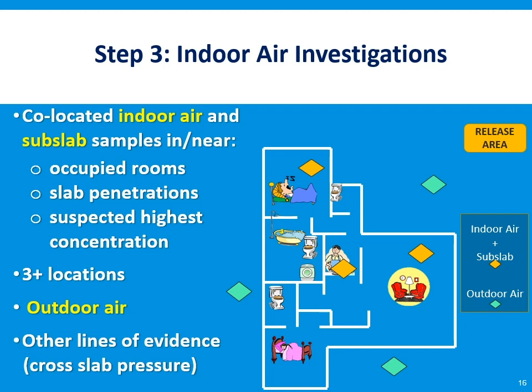Ideally, indoor air and the subslab should be sampled concurrently. The collection of subslab data will assist in the interpretation of the indoor air data. The supplemental guidance recommends the sampling of the occupied rooms, areas where the foundation is penetrated with utilities, and the areas of suspected highest subsurface concentration under the slab. 3 or more indoor air samples should be collected during each round of sampling. Outdoor air samples should be collected concurrently.